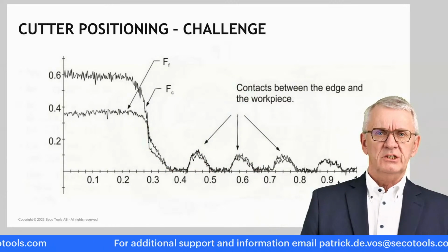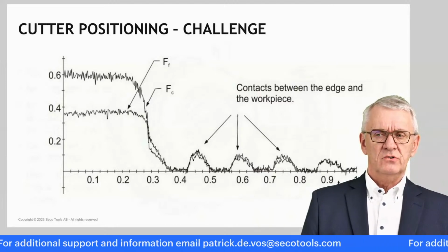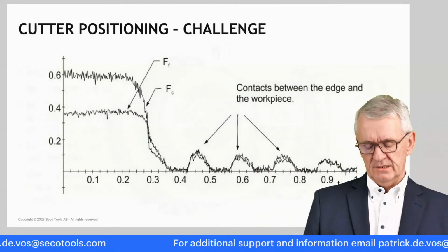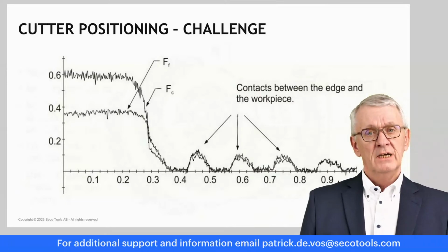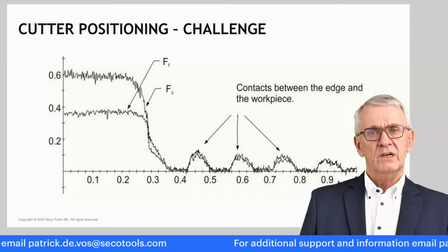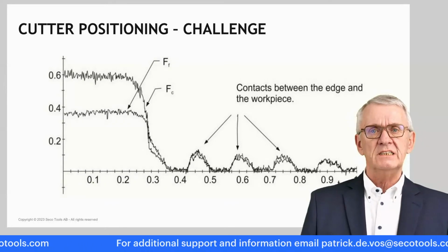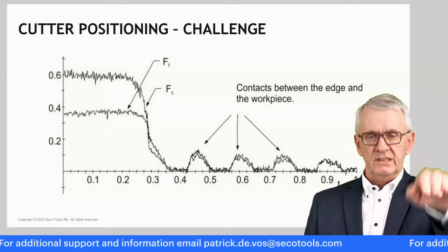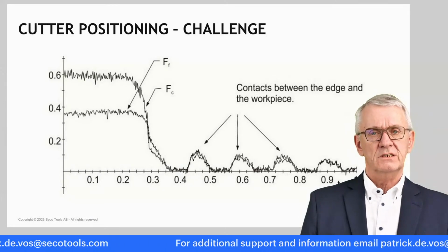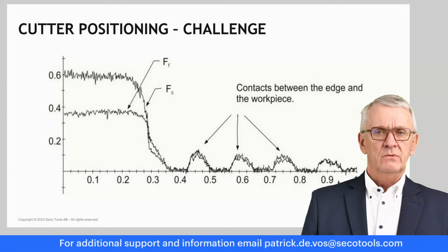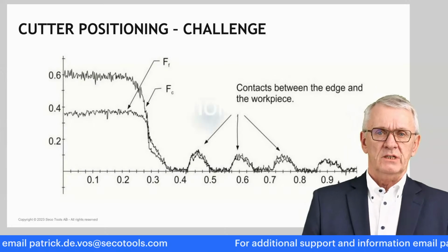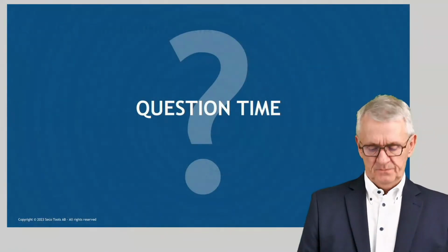Here you have a situation, and I try to let you feel a bit what you are facing. I don't know if there are people here with some experience in the typical example I gave, face milling of the head of a motor block over the cylinder holes, where the cutter starts, what people call, jumping, is doing this. That has to do with the fact that a milling cutter is confronted with 3 different situations at the same time, which leads to different types of loads acting on cutting edges. And as I said, here it's about expertise. But I think